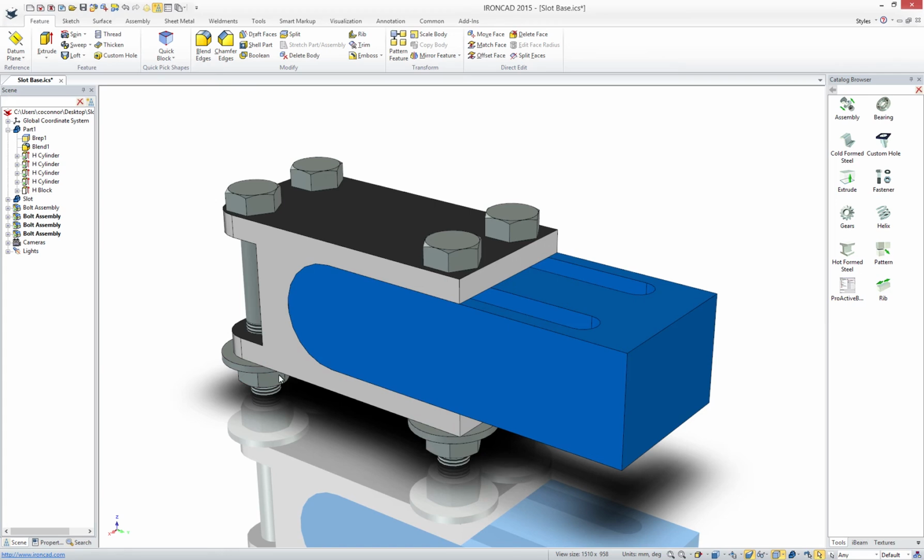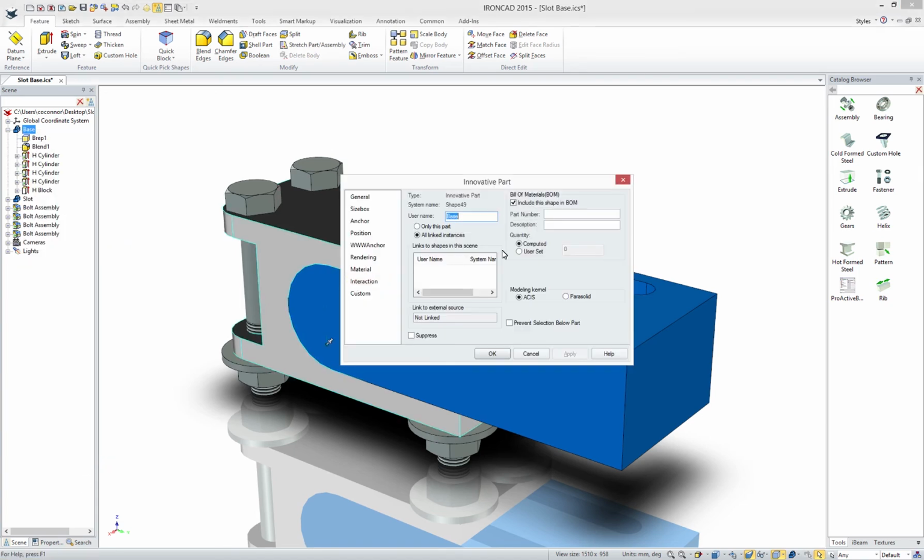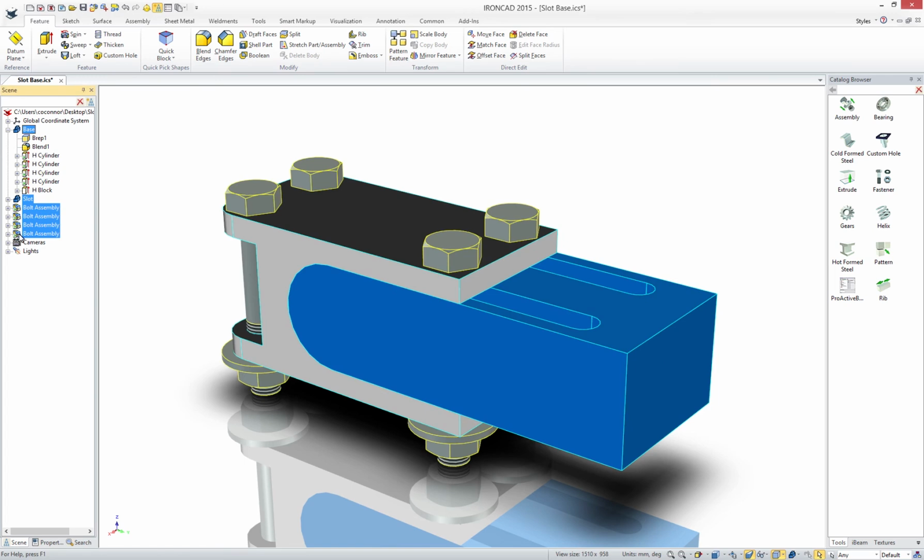Now we can simply use our Tri-Ball to tighten up our fastener and all the linked objects update as well. Now that we have our design, we can freely update our assembly structure to something that has more meaning. We can edit names and part properties such as part numbers and descriptions that are used in bills of materials, and we can create assemblies. IRONCAD gives full power to edit the structure at any stage of the design, whether you are assembling or disassembling.